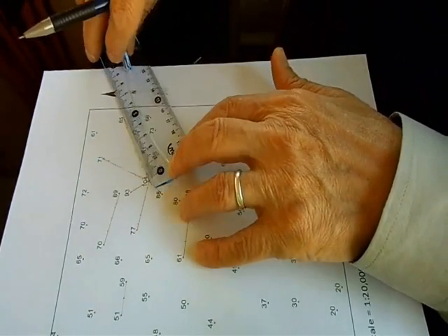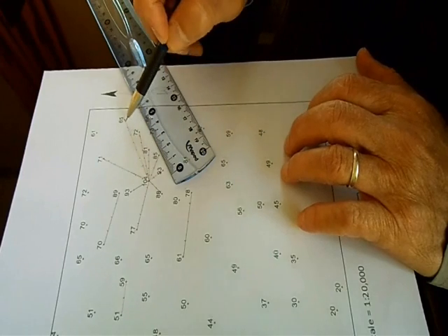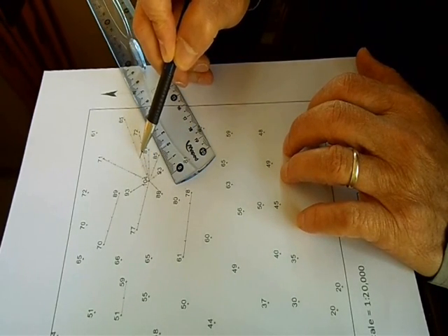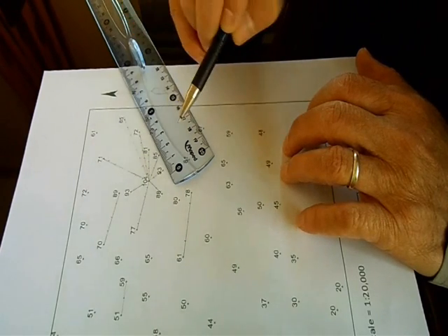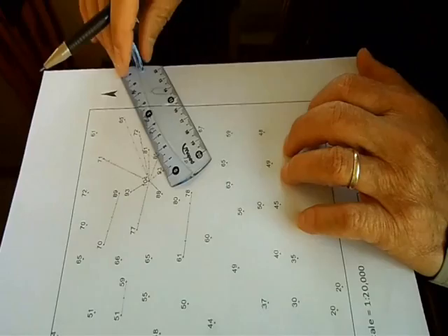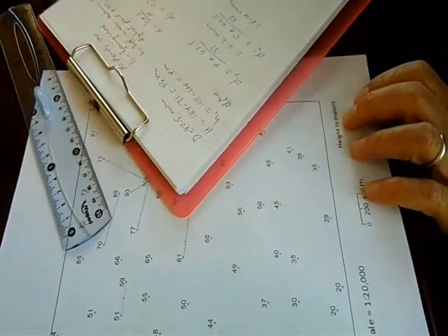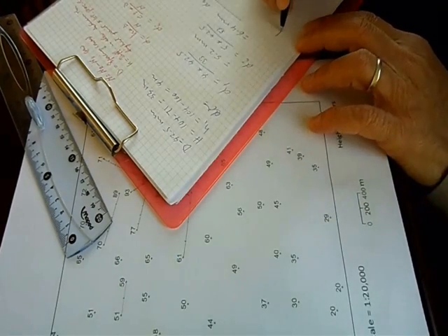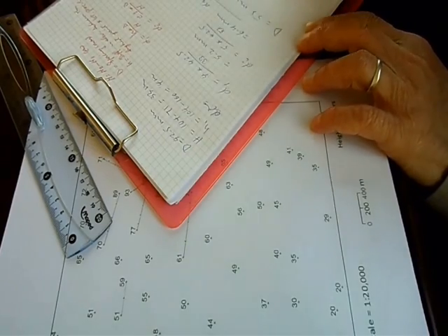Now, the contour lines that are expected to pass from here are 100, 95, 90, 85, 80, 75, 70, and finally 65. So here we have the spacing D equals, as we say, 53 millimeters.